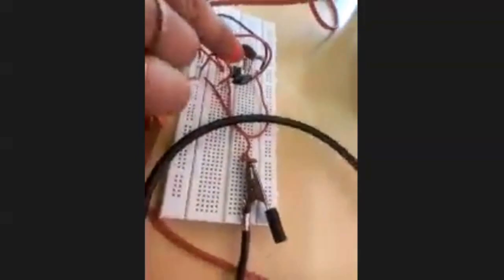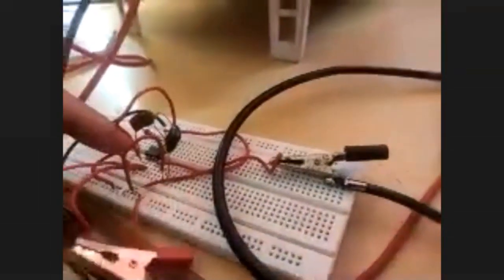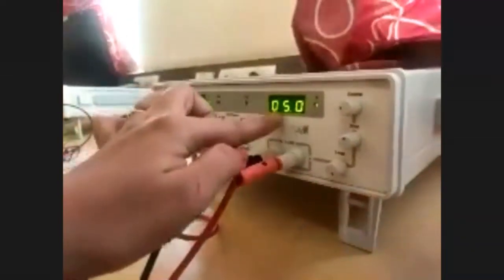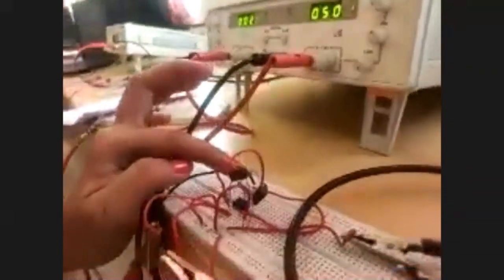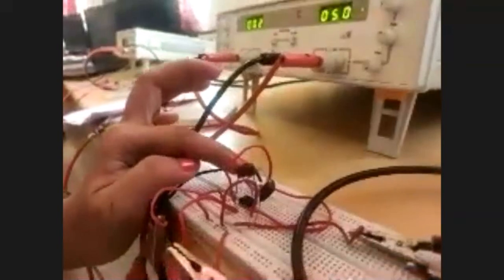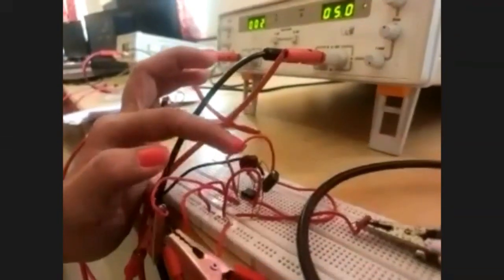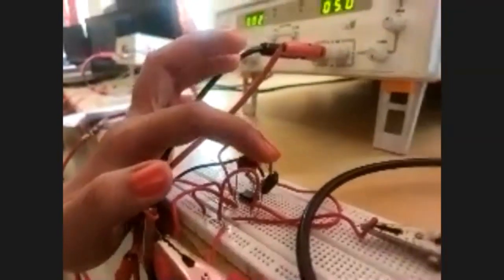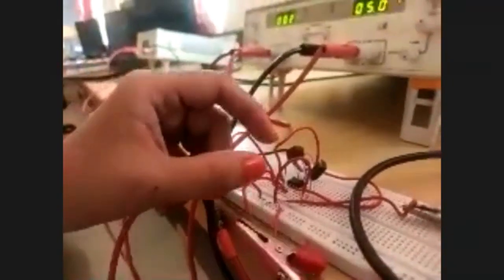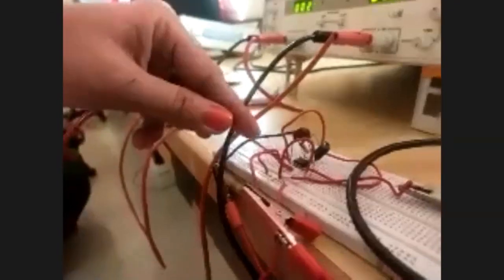Here I am going to connect the 4th pin and 8th pin to the DC power supply with 5 volts. Okay, so it is connected, and two resistors of 4.7 and 5.6 kilo ohm are connected as shown in the circuit, and a 0.1 microfarad and a 0.01 microfarad capacitor are connected, and we are taking the output at pin number 3. The capacitor charging and discharging is across pin number 2.